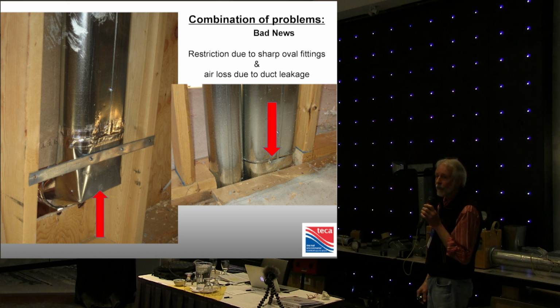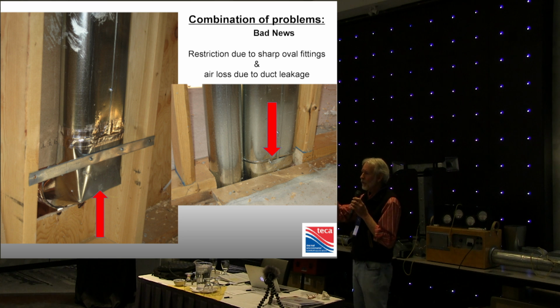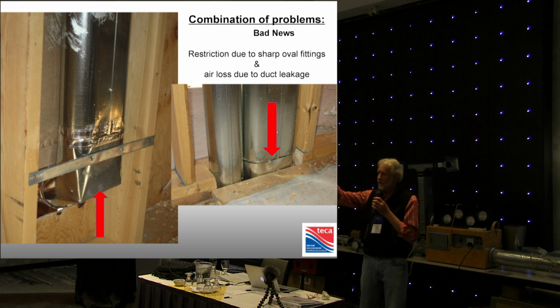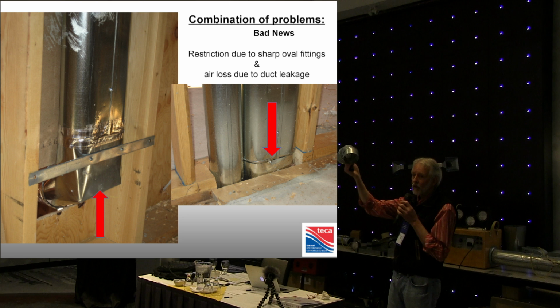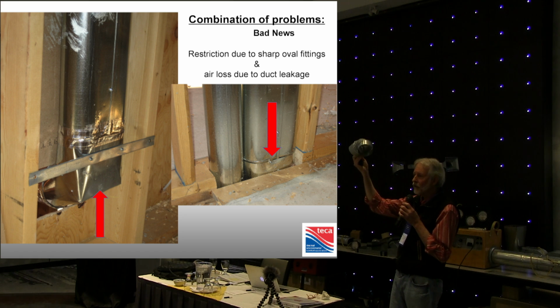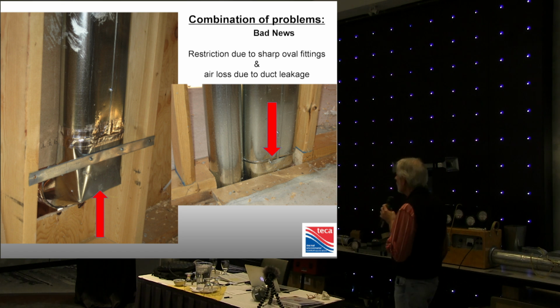And I didn't bring one here, but if you have a 6-inch elbow, it's got 3 adjustable gores. These little swivel things are called gores. And they're beautiful things because you can make them 45 or straight, wherever you want. If you take a 6-inch one of these, and you've got 3 gores, and a joint at either end, there's 96 inches of joint length in the use of this one fitting. And it's real common in ventilation to have a box of maybe 20, 30, or 40 of these going to a house. So you can imagine what's happening for duct leakage contributions. It's just a disgrace.